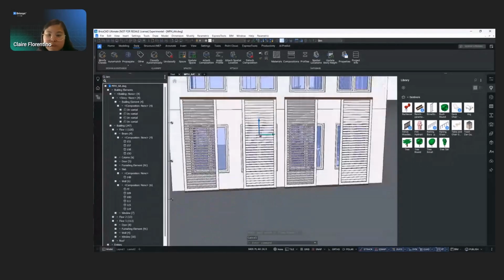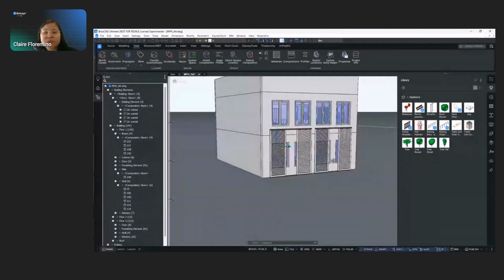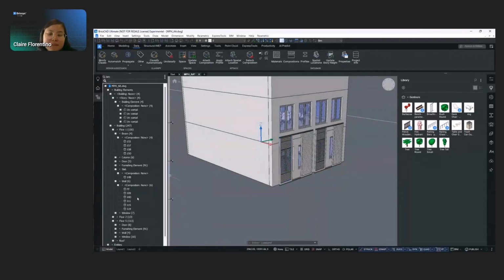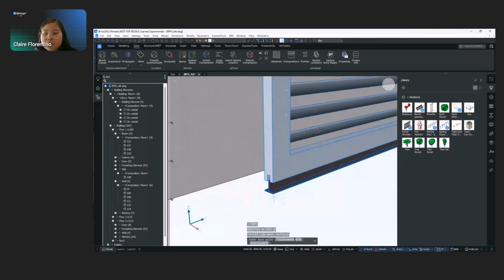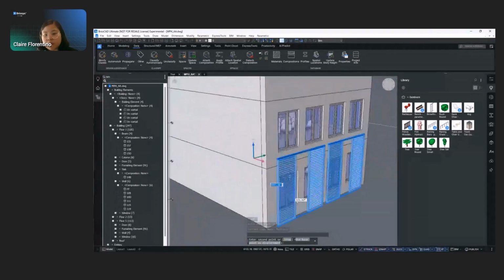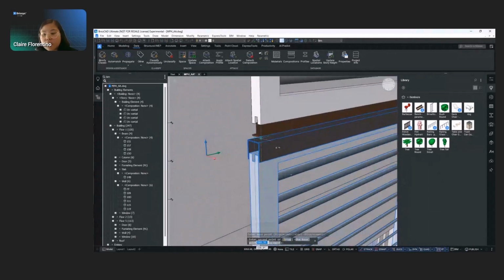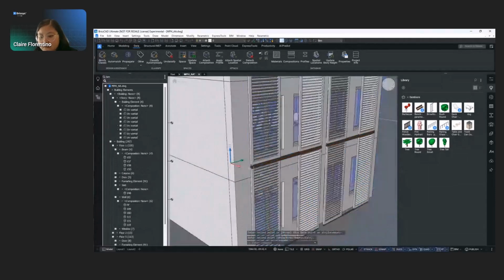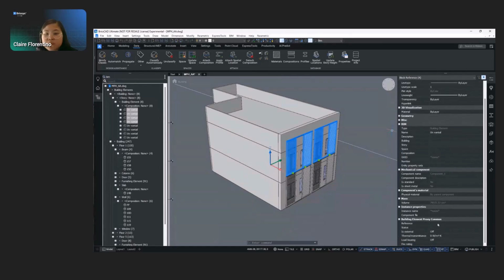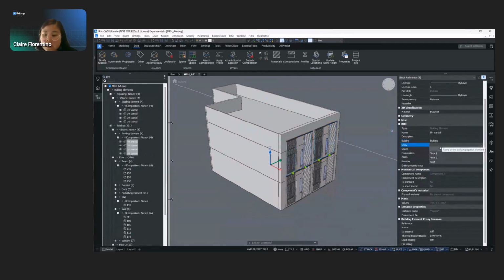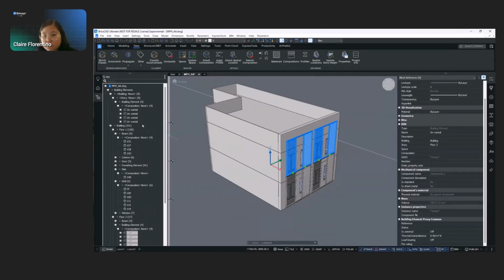And again, if you notice, I keep using the manipulator to just move things around in certain axes, because it's very helpful there. And then, like I mentioned, we'll just also replicate this on level 2. Visually, they're on level 1 and level 2, but since we're on BIM anyway, I'll also want to assign these to the correct story level, so that the information can be included in our schedule later on when we're doing that documentation.